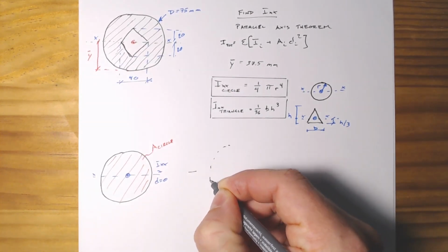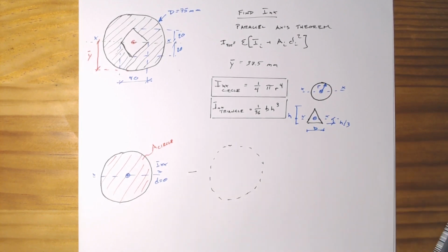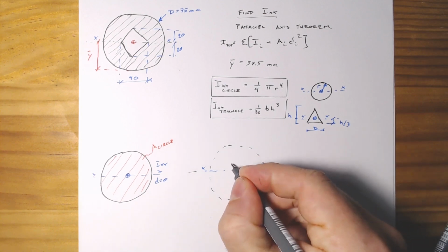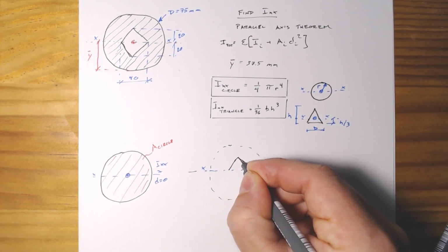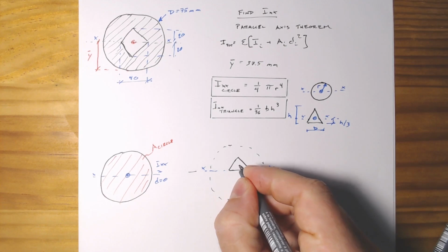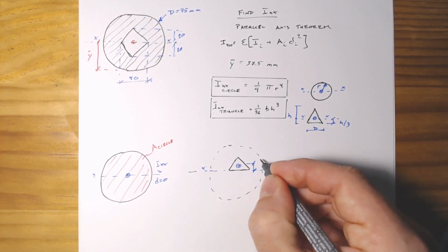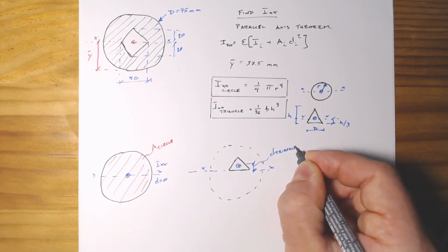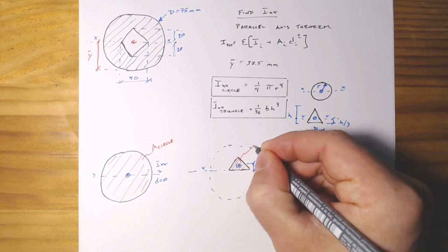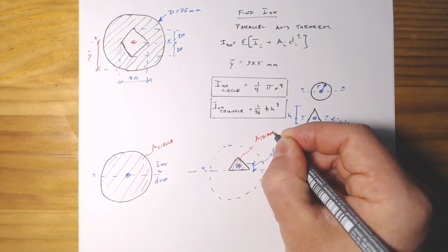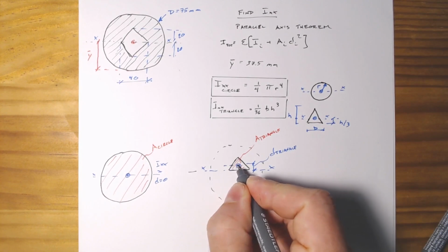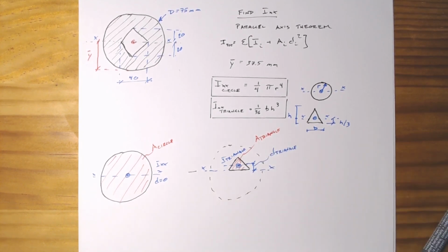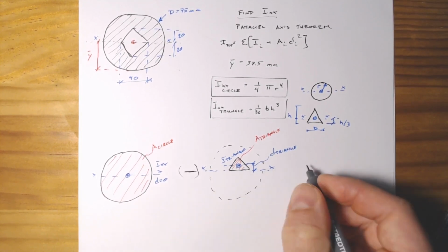in the void, which is punched out here. So we'll draw the exterior of our circle using the x axis of the whole section, and then we'd be looking at subtracting out this triangle, which has its own centroid, so there'd be some distance d triangle, and obviously there'll be some area of the triangle, and it has its own moment of inertia, I triangle, about its own axes. So let's make sure this is a minus,